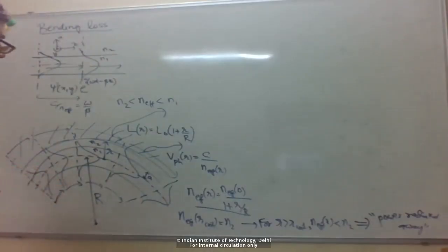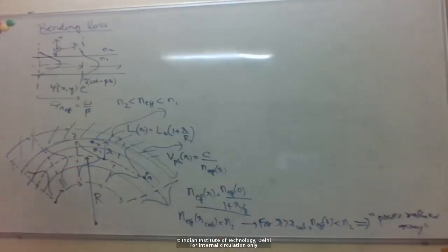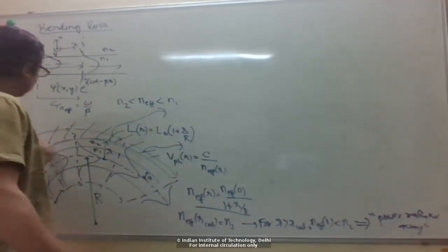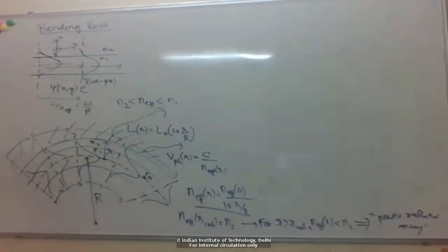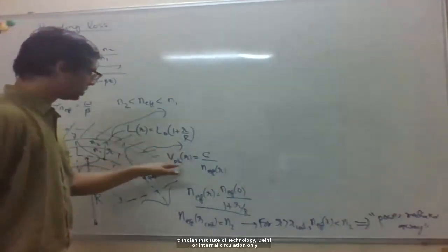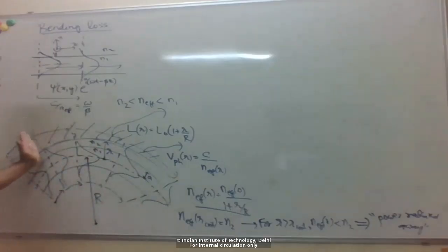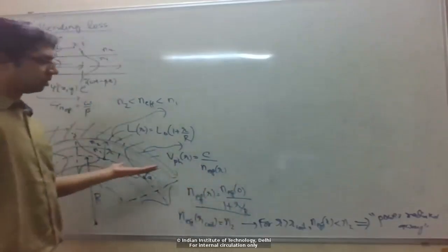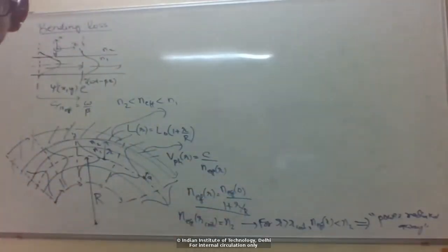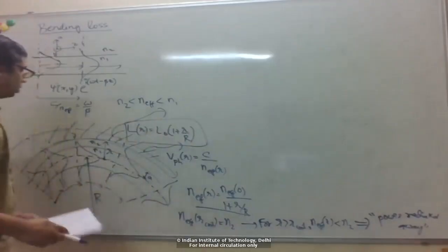Right? So, in other words, there is no truly guided mode for a bent fiber. Okay? Because, again, from the physical heuristic arguments we made, there's no way to maintain a constant phase wavefront. And even if there was some funky way to do this, with an effective index depending on position, even then beyond some critical position, the effective index will have to go below the cladding index, which means it cannot be a guided mode. So this is clear, right?